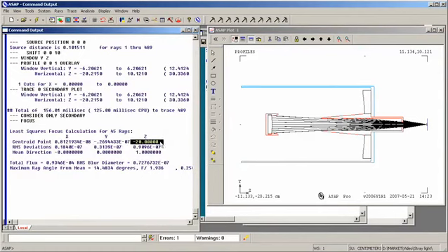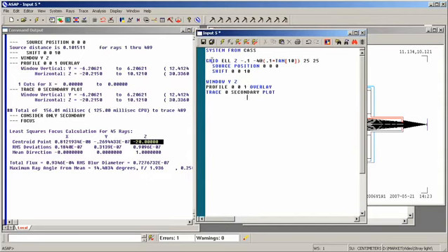We now need to find out the size of that image. We're going to use the same idea, but we're going to use an extended source, not a point source. Instead of our grid, we'll use an emitting rectangle. We'll again place it on the detector, actually just slightly off of it. The size is the same.